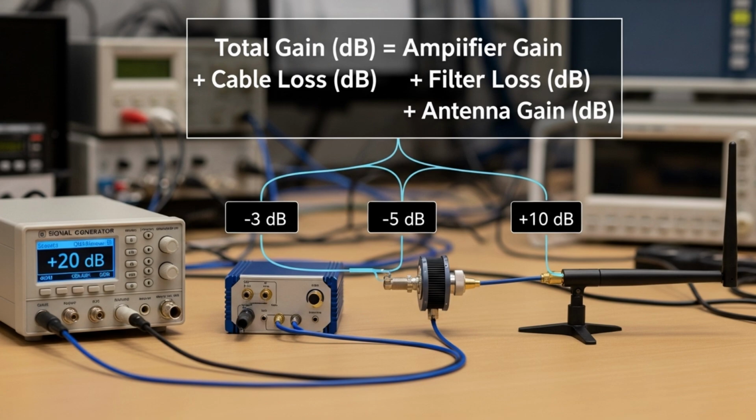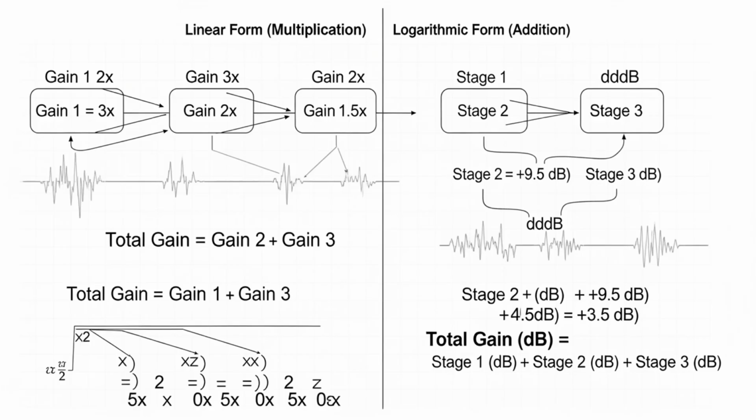In a real RF system, signals pass through multiple components such as amplifiers, cables, filters, and antennas, each contributing gain or loss. In linear form, these effects must be multiplied together, which becomes complex as the system grows. In logarithmic form, each stage is represented in decibels and simply added or subtracted along the signal chain.